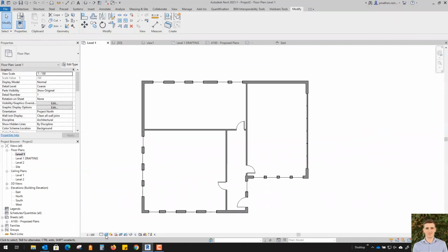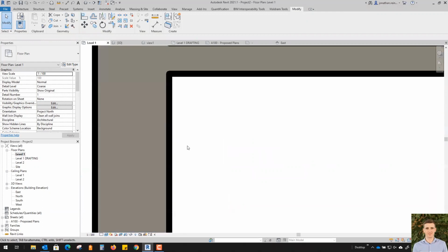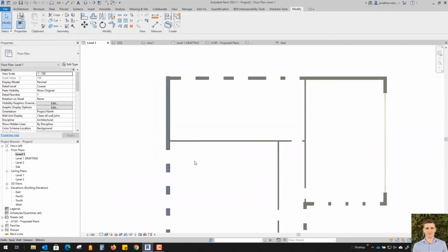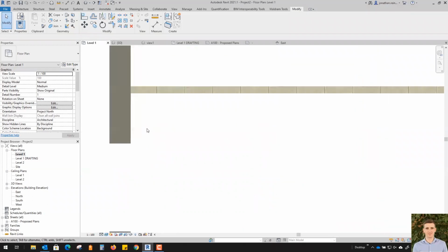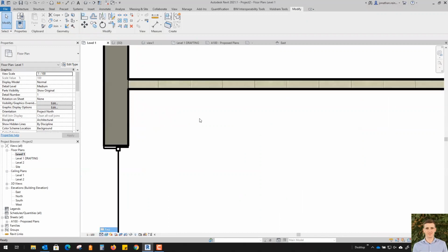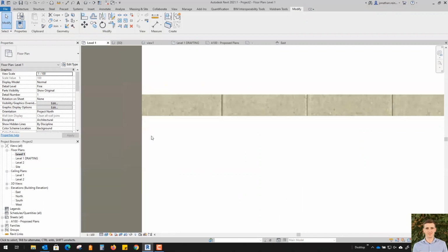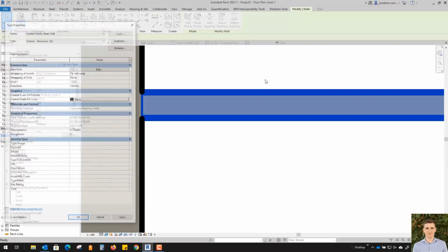Revit also gives you the option for jumping between different visual styles, and these are only view specific. You can see this at the bottom of your Revit user interface, just the second blue box in there from the scale bar on the bottom left. Basically you've got shaded, consistent colors, and realistic. Realistic will show you what we can see here as the blockwork, the actual render image of the blockwork, and shaded will just show you a particular color that you have set in the particular materials